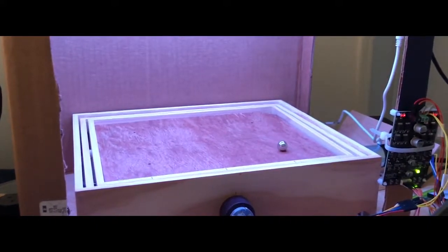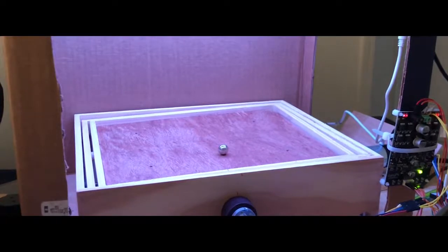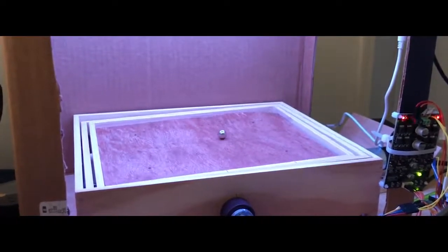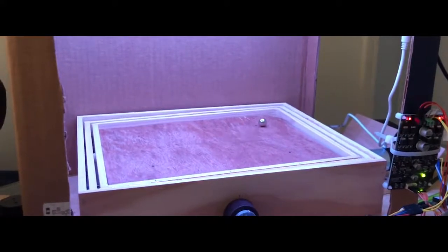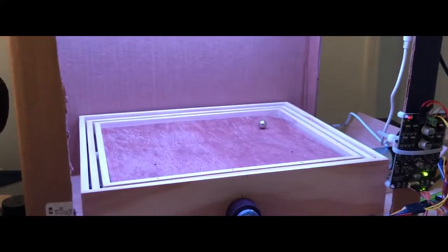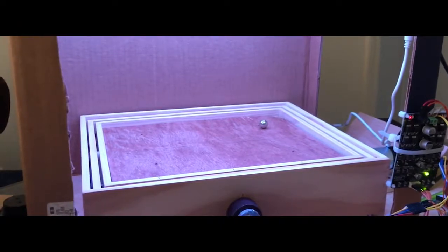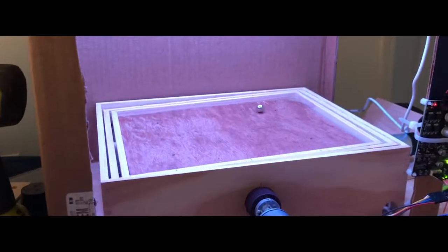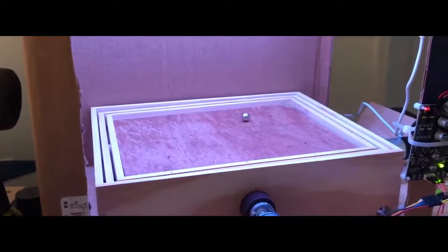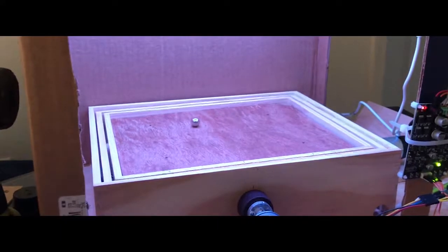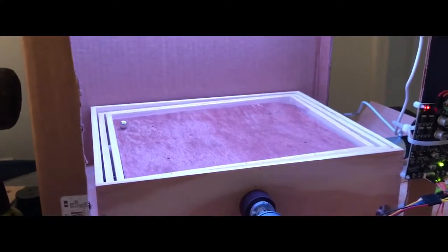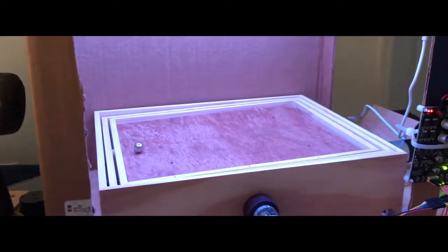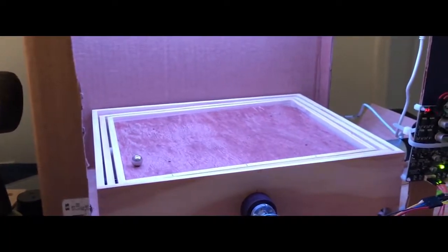The motor controller is used to turn the motor shaft to a desired angle. A desired angle signal is received from the ball controller, which is then fed into the motor's PD controller. This controller determines a PWM signal for the speed that the motor needs to turn and a digital signal for the direction that the motor needs to turn. These signals are then output to the system. The total count from the quadrature chips is then converted into a usable angle and subtracted from the desired angle signal to create the feedback loop for the motor controller.